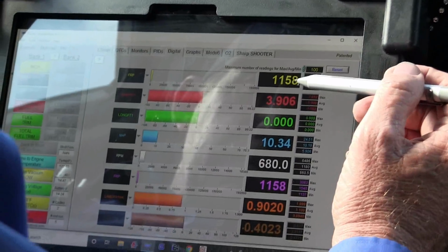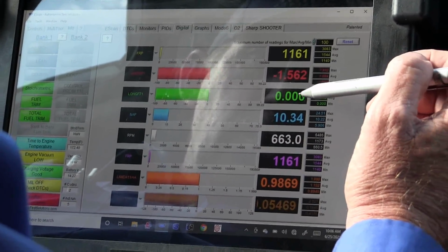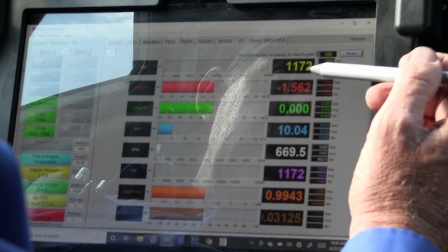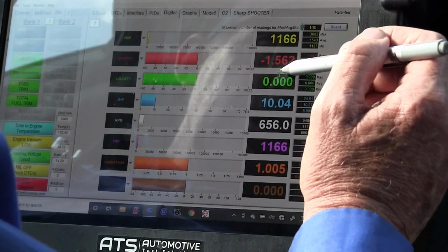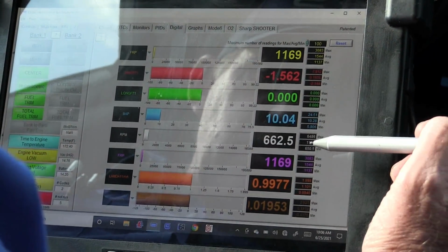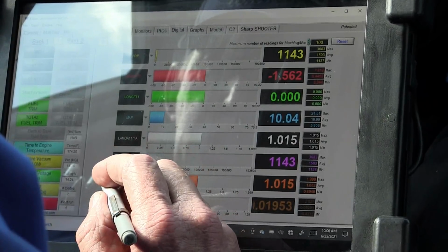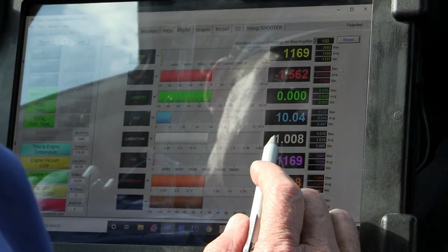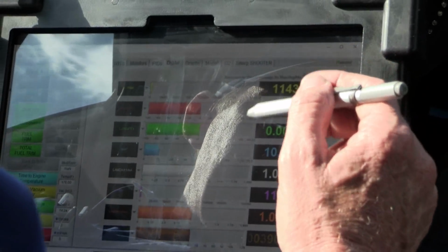So this is my pressure, this is my fuel trim, and this is short, this is long. So these are the main ones I want to look at. So if this pressure drops, I have to trim as well. The other thing I want is the lambda. So I've got a lambda of 1. And if that pressure drops, the lambda is going to go up high and the trim is going to take care of it. That would prove we really have a fuel pressure problem.